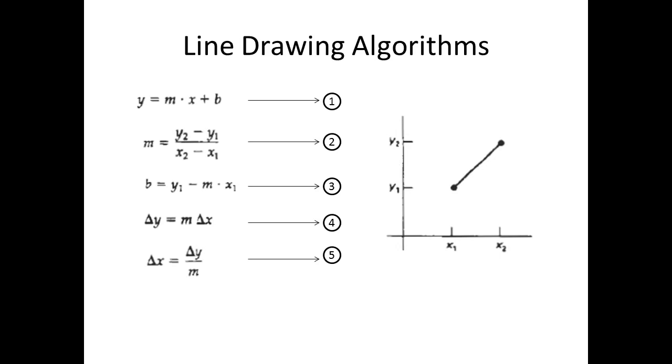With equations 4 and 5, delta y and delta x calculated from the slope have magnitudes set proportional to a small vertical deflection voltage with a corresponding horizontal deflection voltage. For lines with m = 1, delta x = delta y, and the horizontal and vertical deflection voltages are equal. In each case, a smooth line with slope m is generated between the specified endpoints.